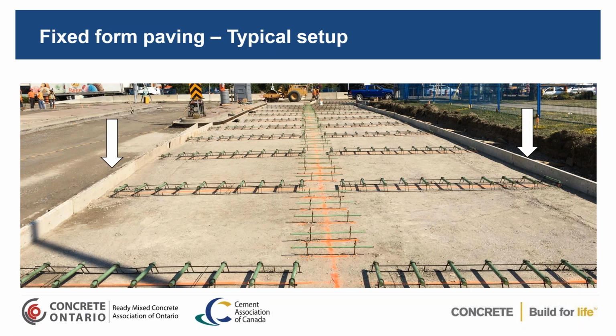So you see the edge of the formwork. And again, these are wooden forms, so you're going to have the form release oil on that to make sure that it doesn't bond. It doesn't pull away some of the concrete when you pull the forms away.